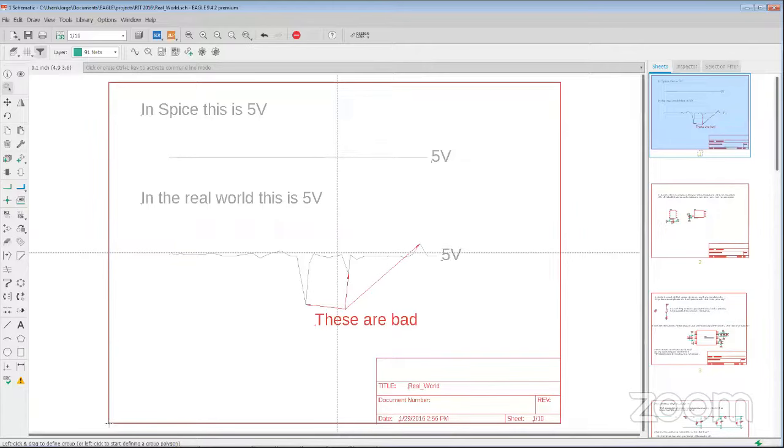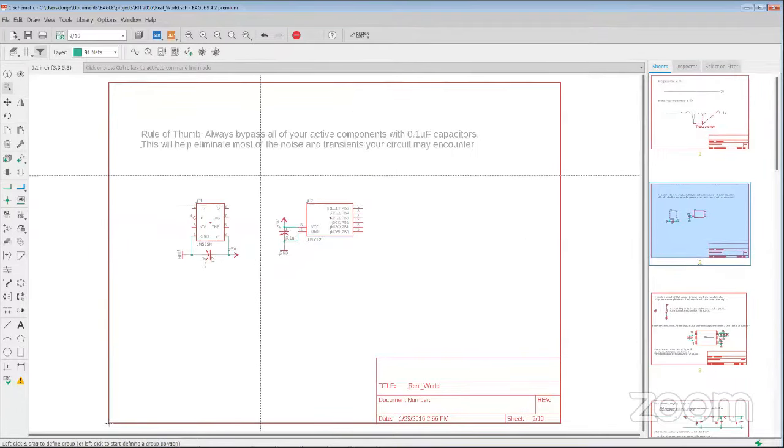So why are we talking about our voltage rails? Well, the first key topic in high-speed layout is bypassing. Any active components, your operational amplifiers, your microprocessor. If you ever look in a high-density BGA, there are many decoupling capacitors, tens, maybe even hundreds, of different values.